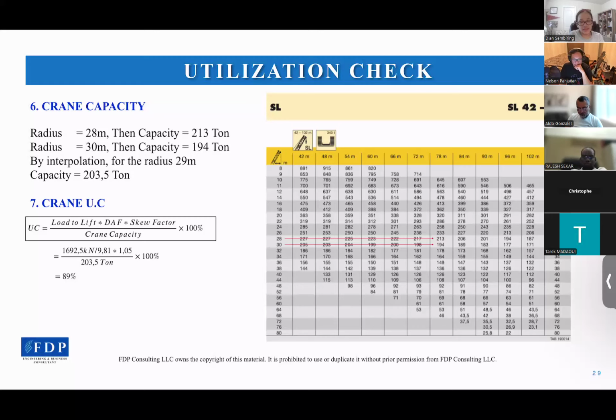And then the second is basic rigging calculation. Basic rigging, we talk about the lifting gear we use for the lifting operation. And the last is mobile crane stability, so we talk about the equipment that we use. So there are 3 components we have to understand very well, and all of this involves center of gravity. You have to understand how to calculate center of gravity and load distribution for the load you lift,